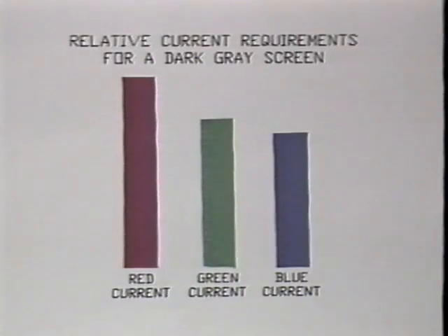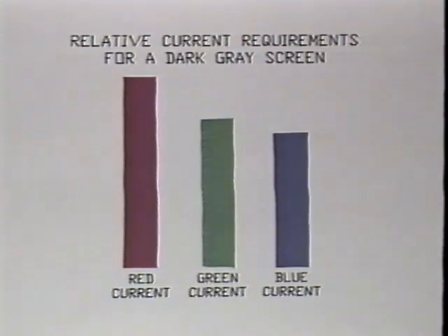The electrical color alignments are collectively called black and white tracking or grayscale. Essentially, these adjustments attempt to electrically compensate for the differences in the 3 types of phosphor on the faceplate. First, we will adjust the cutoff or bias control, which alters the bias of the output transistors so that all 3 phosphors cease to glow at the same input level. If all 3 channels were driven at exactly the same level, the red phosphor would continue to glow at levels where the green and blue had already faded to black.